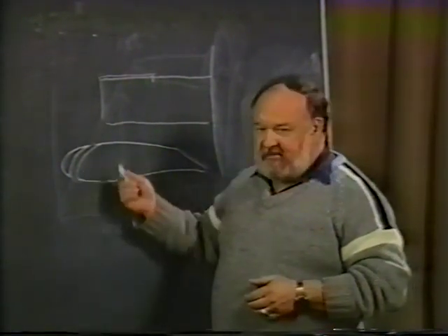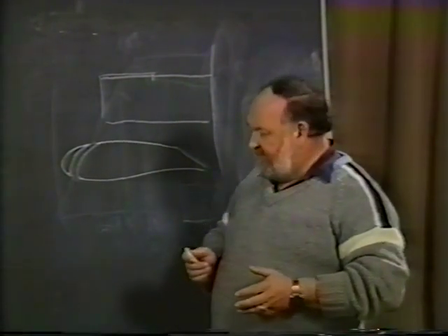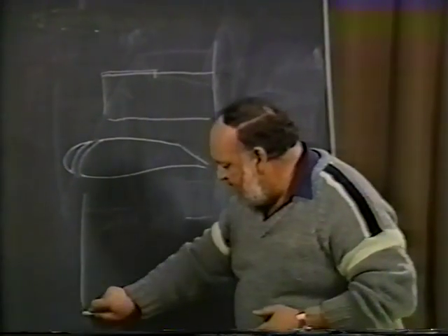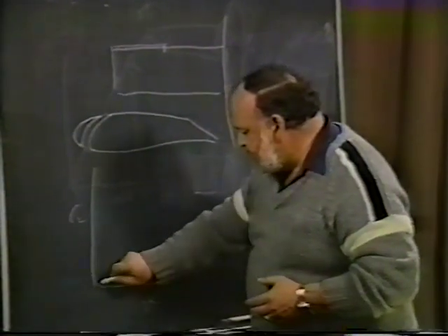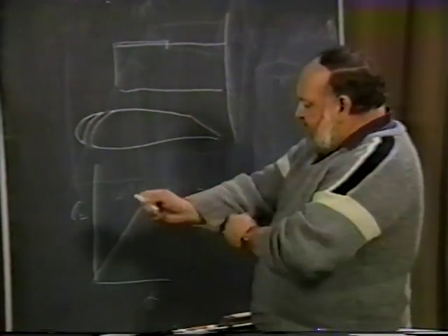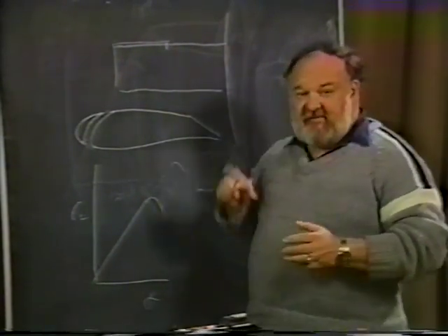But a properly designed slot will give a very definite effect. Go back to the old famous lift curve slope, your CL versus alpha. What it really does is take the original curve and just keep extending it on up, sometimes as much as 5, 6, 7 degrees.